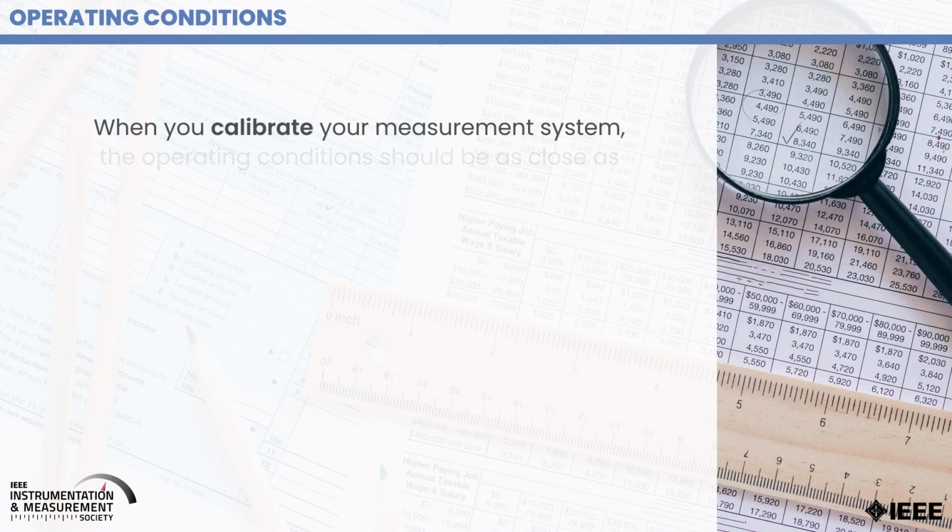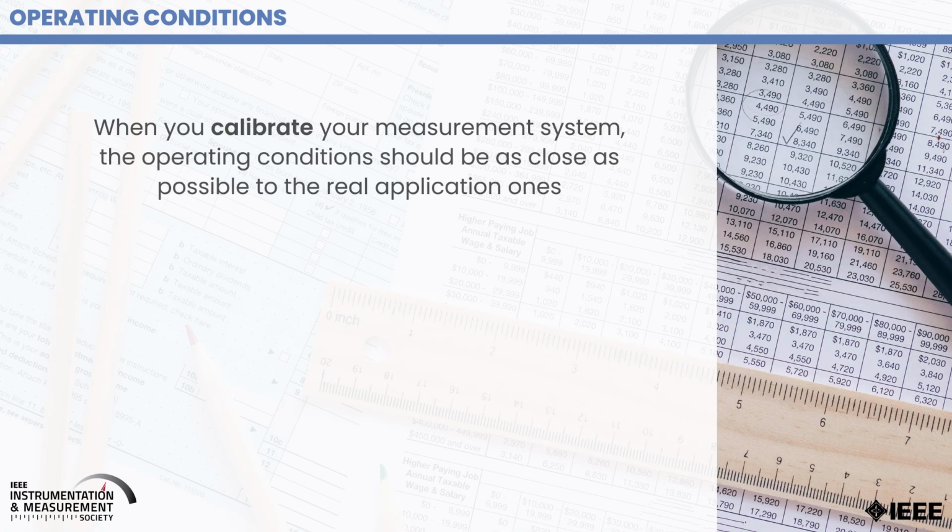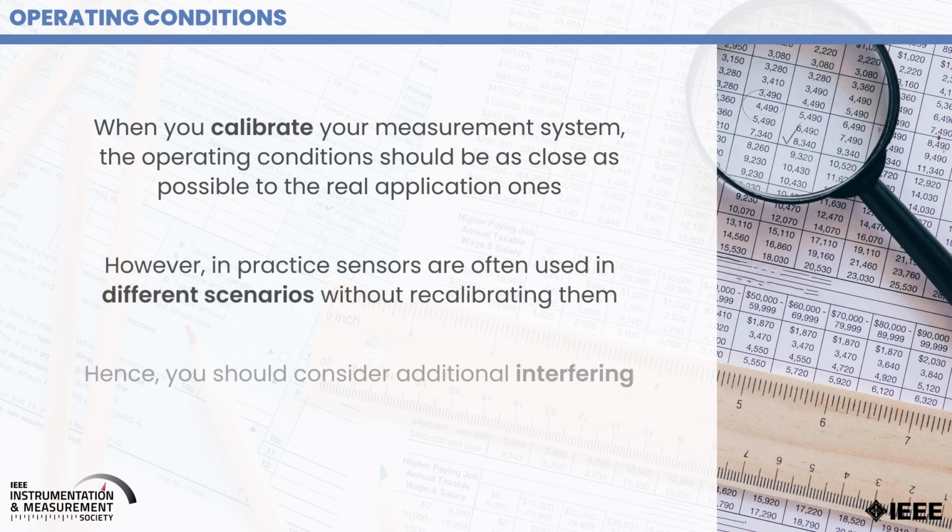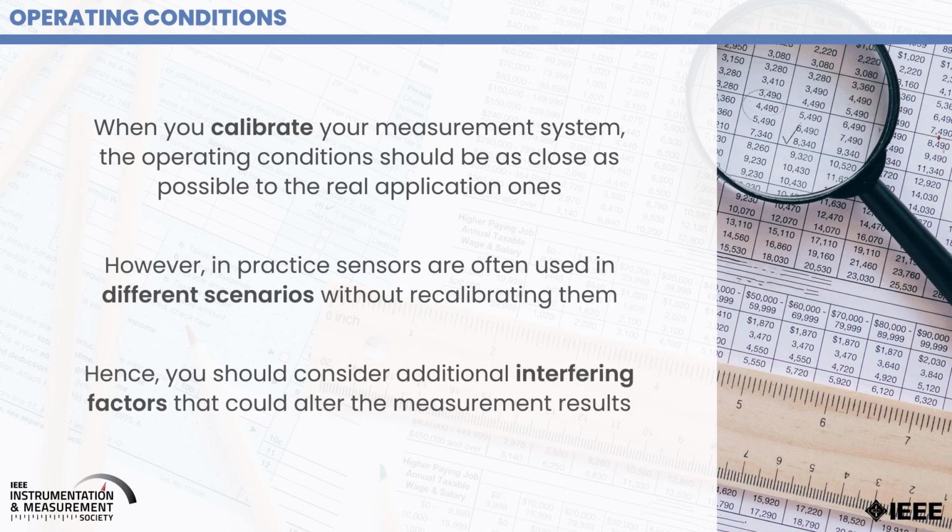Then you have to consider the test environment, which is often different from the one where the equipment has been calibrated. For sure, there will be many interfering factors to be evaluated, each with a different impact on the measured data. Hence, we can perform a sensitivity analysis and focus on the factors with a greater impact to optimize the test conditions.